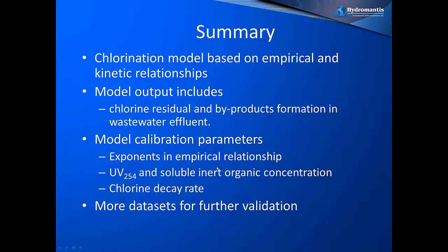Two of the most important model calibration parameters, in addition to the exponents in the empirical relationships, because wastewater properties might be different from plant to plant so some adjustment might be necessary, are the relationship between UV254 and the soluble inert organic concentration, and the chlorine decay rate. So these are the three important parameters that we used in the model calibration. As I said, we are looking at 4 more data sets for further validation of this model.